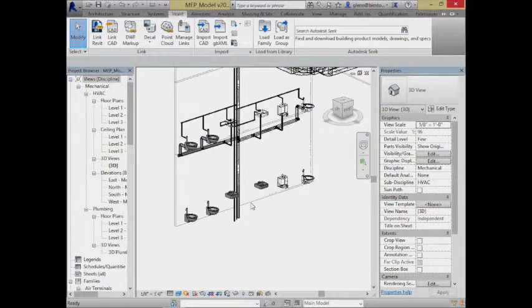Maybe there's a urinal. Those tend to be a little bit higher. Well, toilets in commercial spaces, just so you know, are about 19 inches off the floor, at least for an ADA compliant one. Residential ones are a little bit lower. So if you ever wonder why a toilet in a public space feels like you're climbing up a little bit higher, you are. Then there's a sink over here, and a bowl on the bottom. So we've got some different fixtures in here.